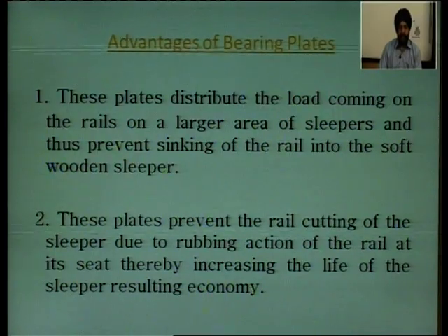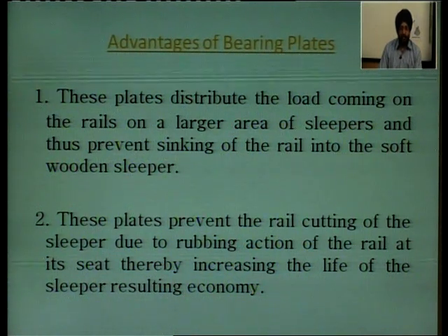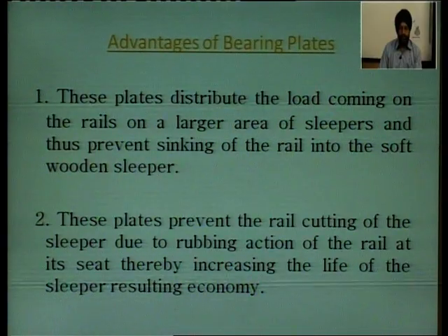Secondly, these plates prevent the rail cutting of the slipper due to the rubbing action of the rail at its seat, thereby increasing the life of the slipper, resulting in economy. We know when the load is coming over the rail, there is a rubbing action of the rail at its seat.